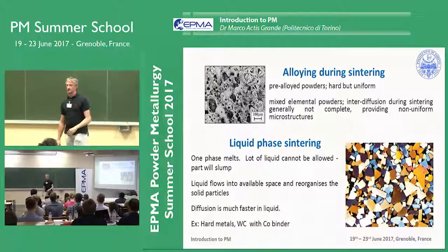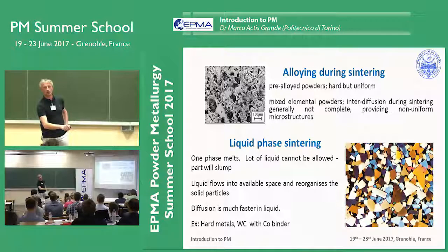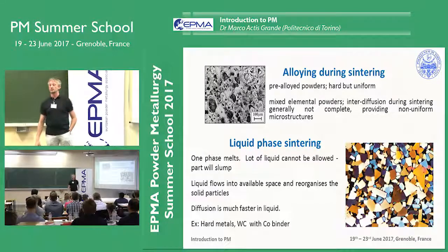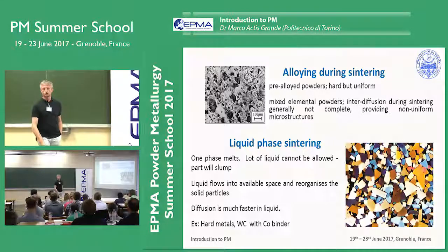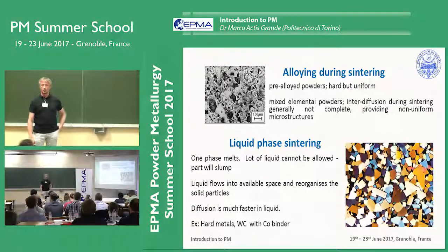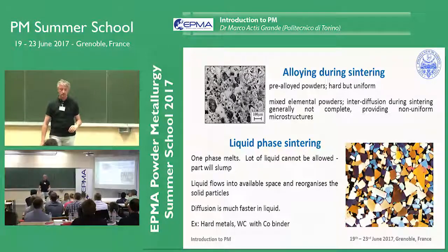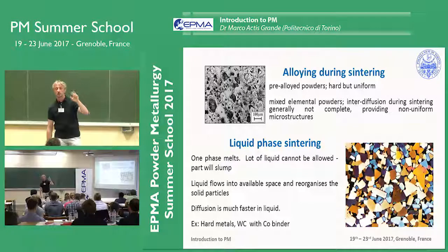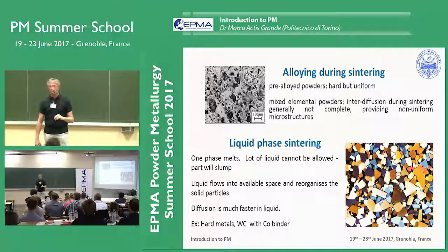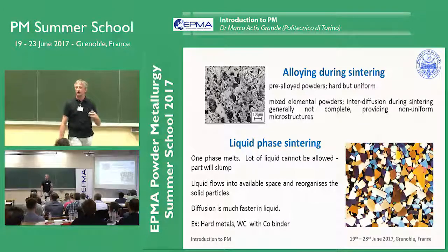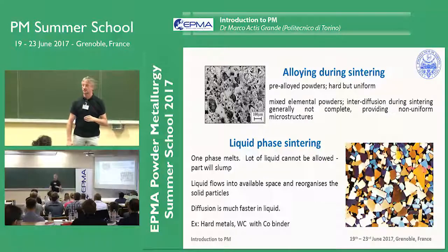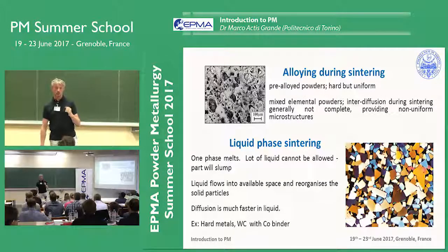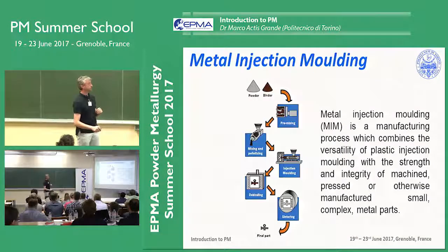Now, what can happen during the sintering? New components may be formed. Actually, there can be some diffusion happening. There can also be some liquid phase forming. If you go back to the definition that I was providing before, it's the ISO temperature below the main constituent melting temperature. It doesn't mean that nothing can go on melting. And this is something, as you will see again tomorrow, which is quite important for the definition of some properties of sintering materials.